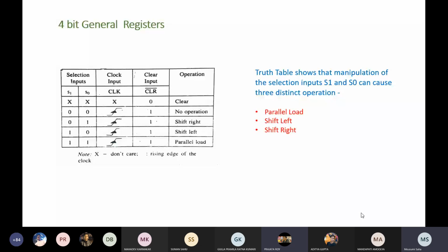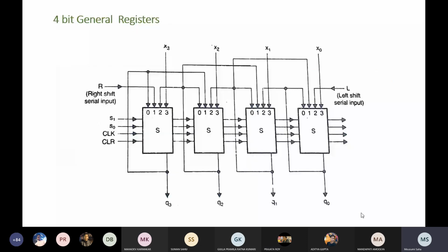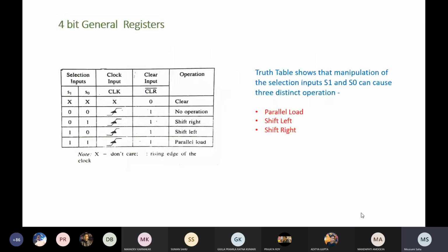This depends on how you have designed it, and maybe you can design with the help of level triggering. Normally we know that level trigger means a latch. In our execution unit, many times we use a latch circuit, that is, a level trigger. So it depends on what type of execution unit you want to design and what your requirement is. Depending on the requirement, you can use a different type of flip-flop or latch structure.